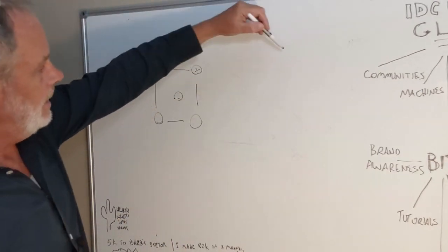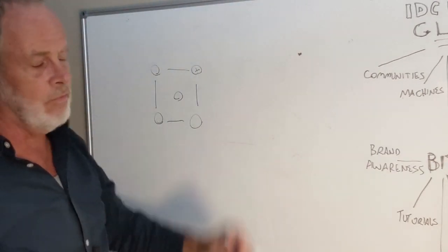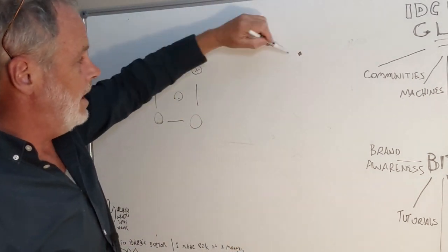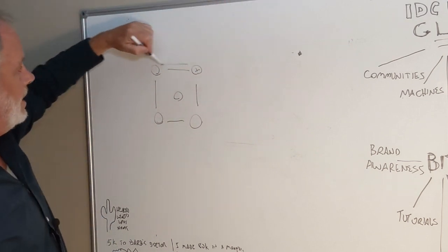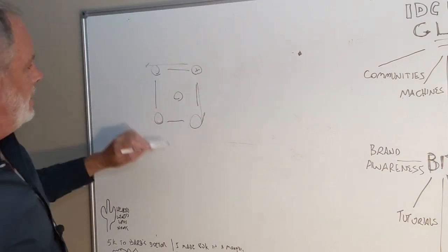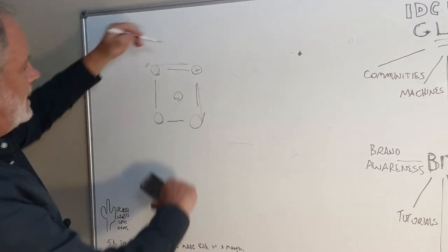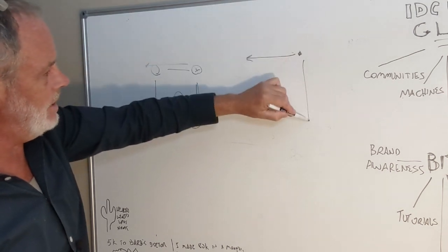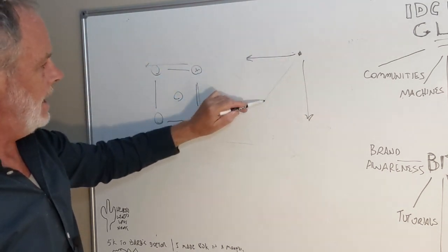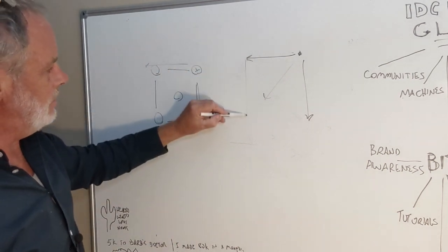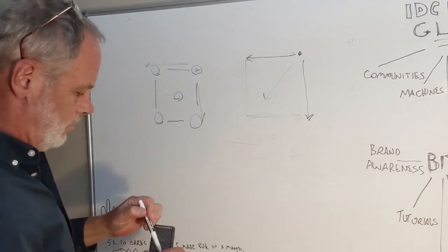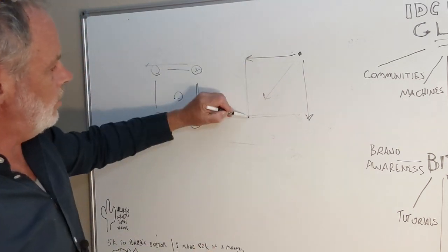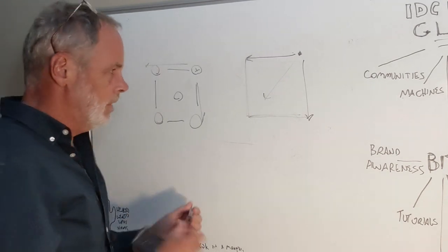So it is now going to create the rectangle from the coordinate that we tell it, which is right here, and it's going to build it that way and that way. So your rectangle is basically like this, and it's referencing that top corner. The rectangle is going to build out that way, and the far corner will be out like that. So the software will build it from the upper right corner down that way.